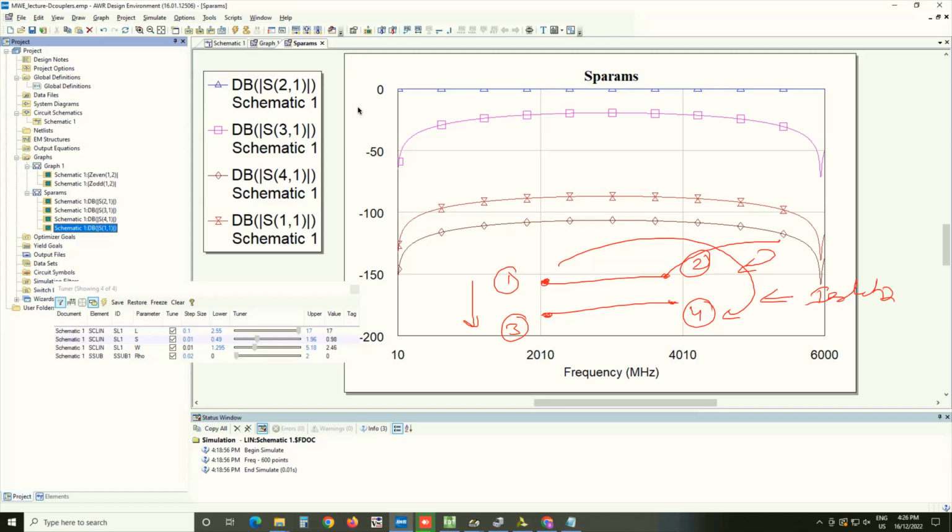So it's that ratio you want to maximize to be able to get a good handle on these reflected and incident quantities. And this becomes a very important component inside a vector network analyzer, which is what this kind of measurement does. And often they have something called a dual directional coupler, which is sort of two of these directional couplers connected back to back. And in the last lecture, I will be discussing briefly a few scattered special topics, where I'll talk about this dual directional coupler as well.